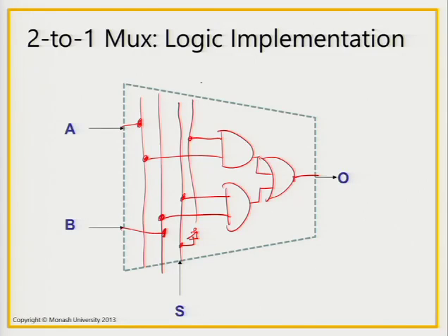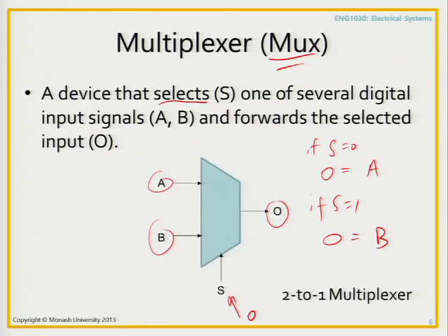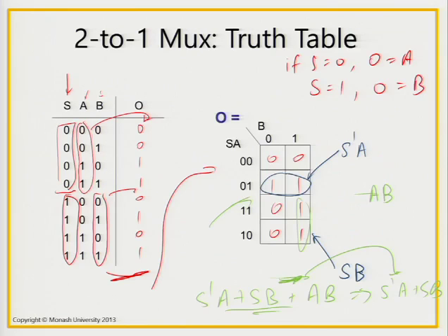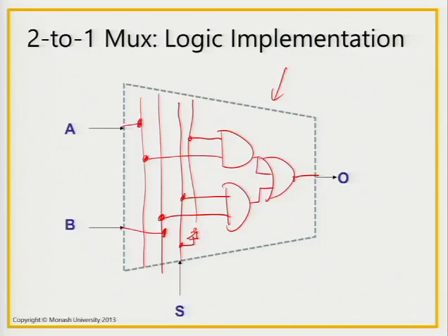Okay? And I've drawn this box outside a little bit like a, well, it is a trapezium, because that is actually the symbol for a multiplexer. So if I was drawing a symbol for an op-amp, you know, it is a triangle with some pluses and minuses on it. A symbol for a digital multiplexer is actually a trapezium where you've got the inputs on the large side and the output on the small side. Okay, great. So now you've got little components for a computer that can add and it can select inputs. Okay. That's all.